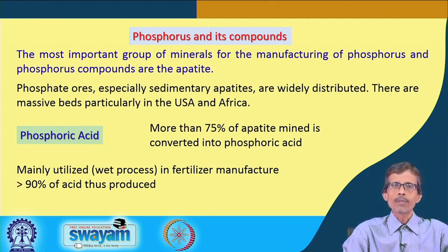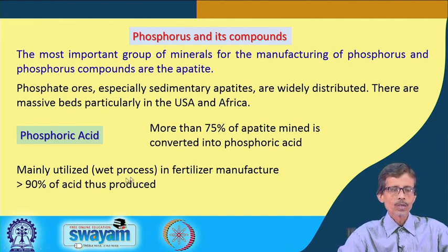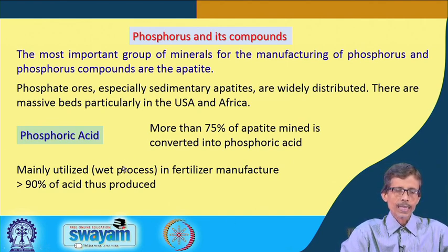What is that NPK? N is for nitrogen, P is for phosphorus, and K is for potassium. Potassium can come as the corresponding salts, as potassium ions, but before that, what we have seen earlier is nitrogen. Now, today we will be talking about phosphorus. In making fertilizer we always use phosphoric acid, and one such particular process is known as the wet process.